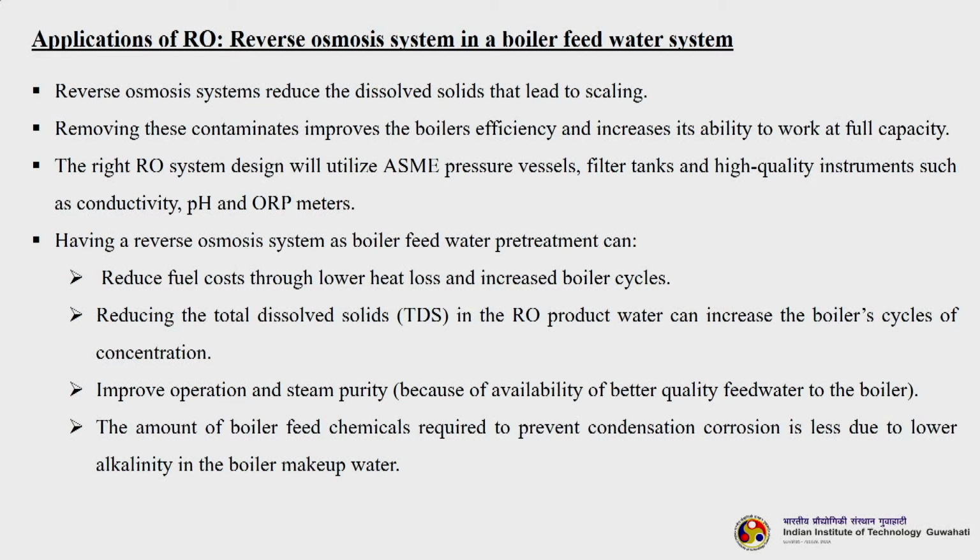The right RO system design would utilize ASME pressure vessels, filter tanks and high quality instruments such as conductivity, pH and ORP meters. Having a RO system as boiler feed water treatment can reduce fuel cost through lower heat losses and increased boiler cycles, by reducing the total dissolved solids. This is another very important thing: the RO product water can increase the boiler cycles of concentration as much as the TDS and scale forming compounds you are removing. So, you are basically increasing the life of the boiler.